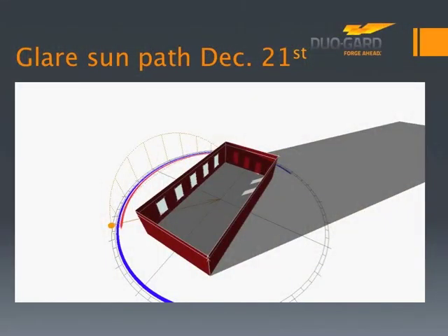An illustration of a glary space here is the south side windows, and you can see as the sun on December 21st runs through the projected time for Detroit, on the display that the light travels throughout the space all day long, but it never leaves it. And there's glare somewhere inside the space all day long. So that's an issue for solar heat gain, it's an issue for contrast, it's an issue for a comfortable space to be in and occupant behavior.